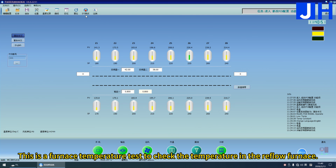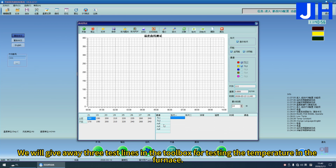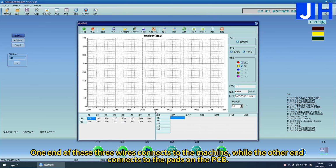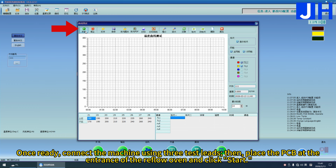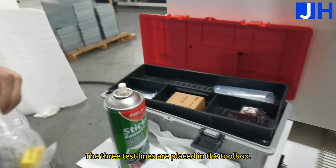This is a furnace temperature test to check the temperature in the reflow furnace. We give away 3 test lines in the toolbox for testing the temperature in the furnace. One end of these 3 wires connects to the machine, while the other end connects to the pads on the PCB. Once ready, connect the machine using 3 test leads. Then, place the PCB at the entrance of the reflow oven and click Start. The 3 test lines are placed in the toolbox.